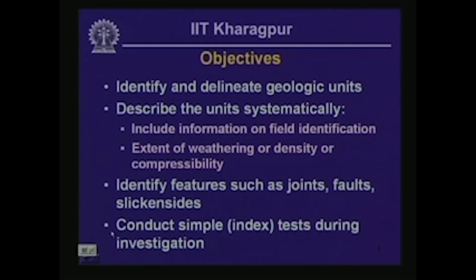Now, we consider the objectives of the subsurface investigation activities themselves. Why do we undertake subsurface investigation at all? What do we want to find after we conduct a subsurface investigation program? First of all, we are interested in identifying and delineating geologic units.